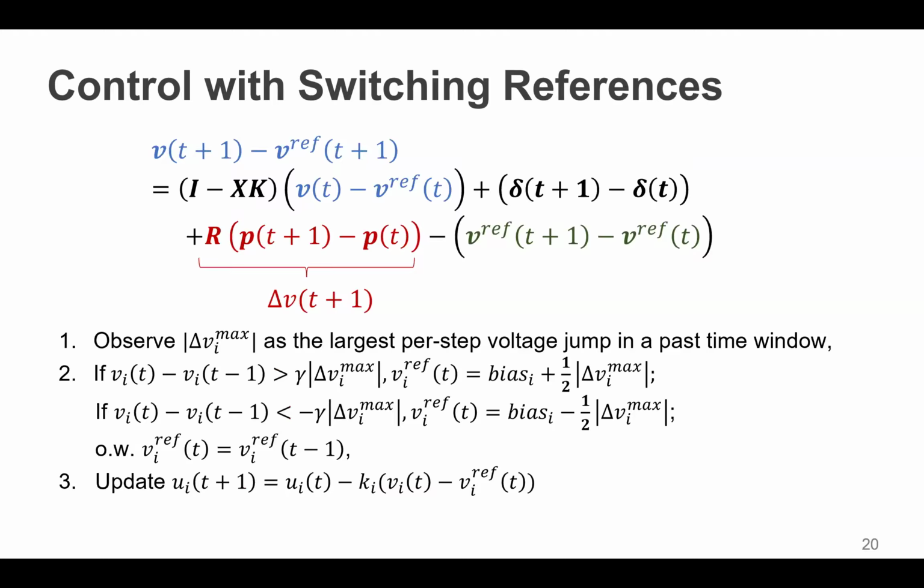So then how the algorithm is implemented is essentially that, so now, what is the delta? The delta term is the model error, the model error from the linear flow model to the original DistFlow model of the system. Because here we linearize the DistFlow model, so that is exactly the model error.